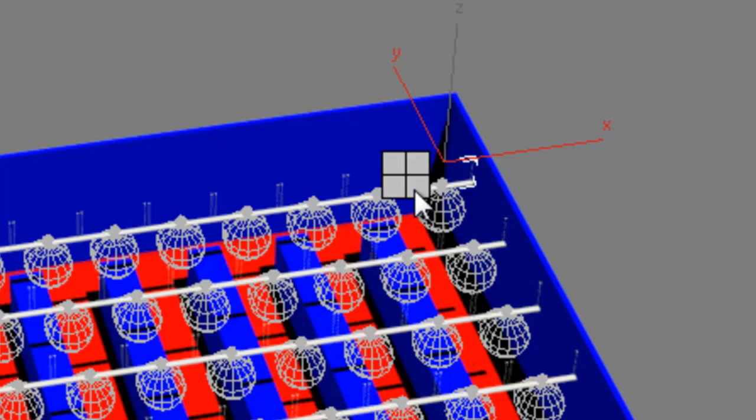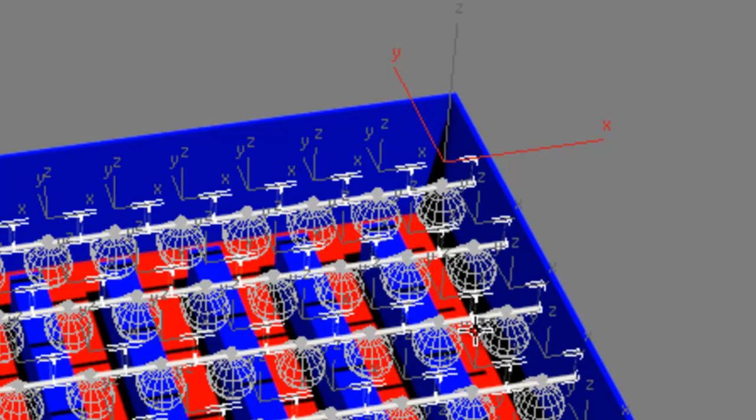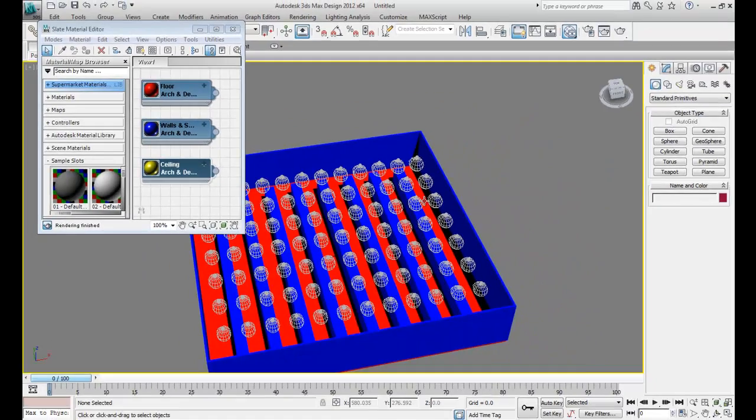In order to get the lighting analysis to perform properly, you need to select all of those fixture objects and delete them so it doesn't block the reflections up to the ceiling. So what you can do is select one of those pendants and right click and select Similar, and it will select all of the pendants, and you can just delete them in one action.